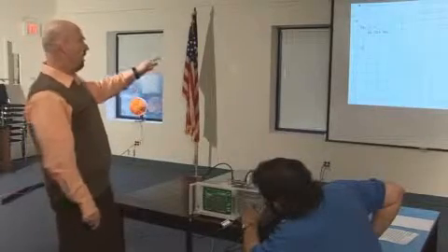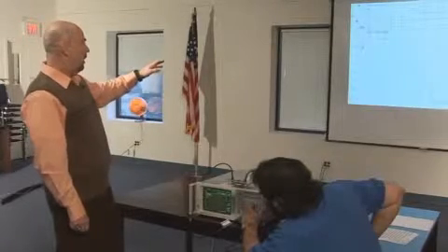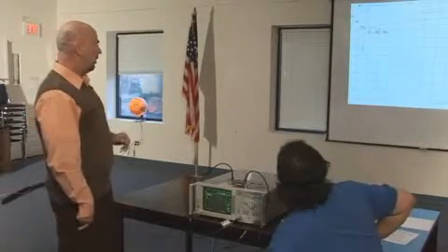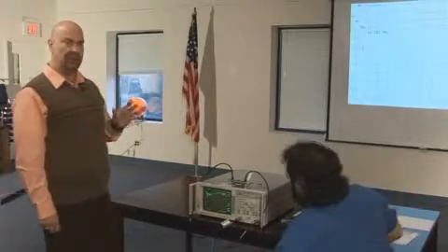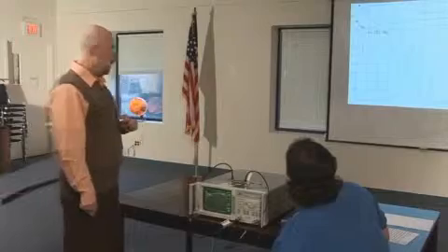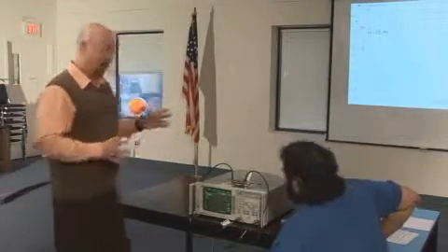So what does it say? I have a problem around 43 megahertz. If I put the marker from the analyzer, you can see it's about minus 30, 35 down, which means it'll attenuate that signal by that much. And if you're unlucky enough for that to be your problem signal, then it'll go away.